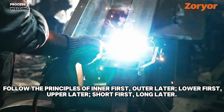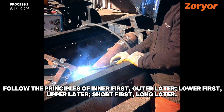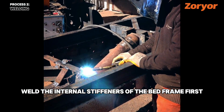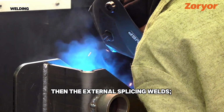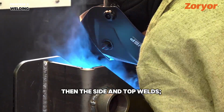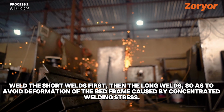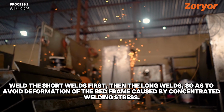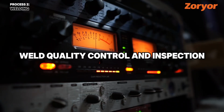Welding sequence. Follow the principles of inner first, outer later, lower first, upper later, short first, long later. Weld the internal stiffeners of the bed frame first, then the external splicing welds. Weld the bottom welds first, then the side and top welds. Weld the short welds first, then the long welds, so as to avoid deformation of the bed frame caused by concentrated welding stress. Weld quality control and inspection.